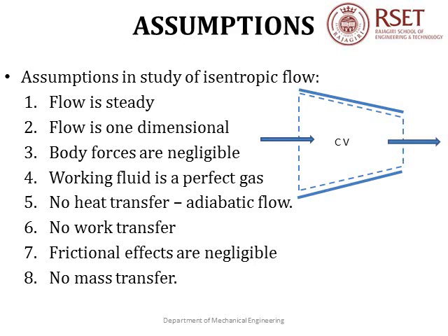Now I told you that the isentropic flow is used to study flow through variable area ducts, that are used as nozzles and diffusers. They are of very short length and the fluid travels at a very high velocity through these ducts. Because of this, the flow process takes place at a faster rate. Hence, we can assume without any error that there is not enough time for the exchange of heat between the system and the surrounding, and hence we can say that the flow is adiabatic.